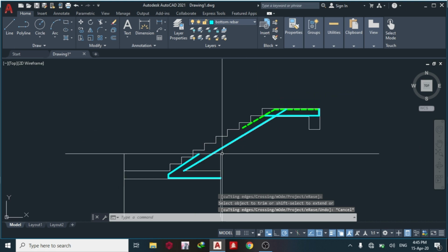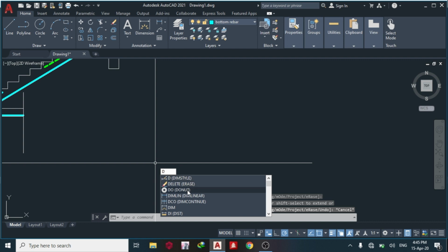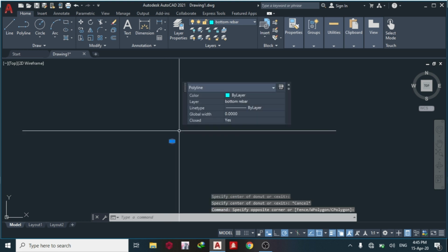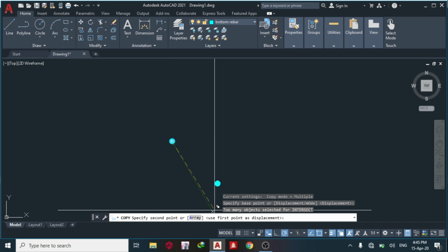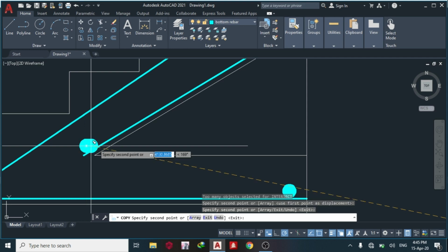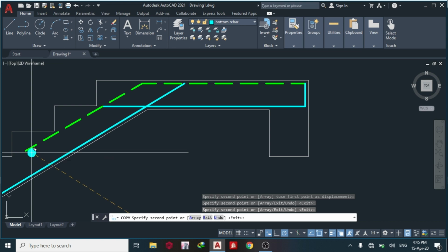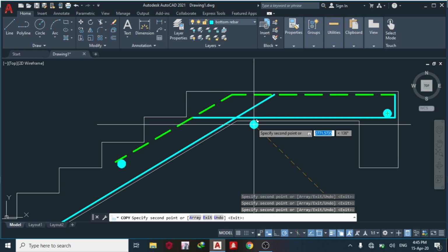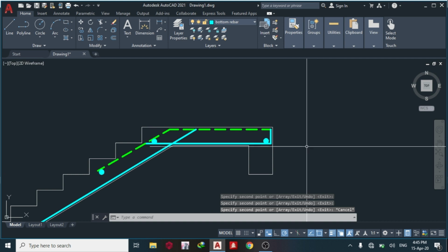Okay. So the next thing I'll do now is put my distribution bars in this direction. So let me just use donuts. The donuts 25, 25. Okay, so I'll copy it and paste, then distribute it. I need one here. I also need one here. I actually need one at this point. I need some here, and I need at the bottom here. Let me use this bottom here so that you understand what I'm doing.